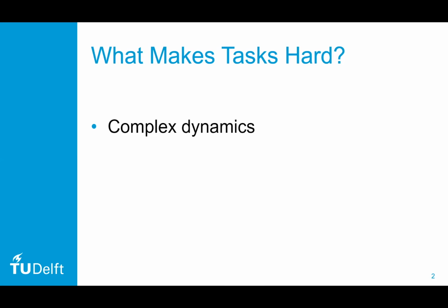What Erwin did this morning is show a whole bunch of simulators, but what he didn't mention explicitly is that one of the big points of difference between them is typically how they model contacts, impacts, frictions, and these kinds of things. So as soon as you want your robot to have physical interactions with the environment or an object, it gets quite a bit trickier to simulate. Then you have the choice to either make it very robust and do a whole bunch of domain randomization, potentially at the loss of performance.